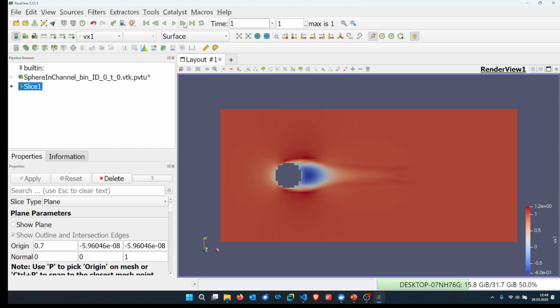Well, we see that for the supercomputer simulations that we run, like atmospheric boundary layers, we need additional viscosity. Basically, we need subgrid viscosity, because otherwise the implicit viscosity, like the kind of implicit LES that is added by the limiter, for example, is not enough.